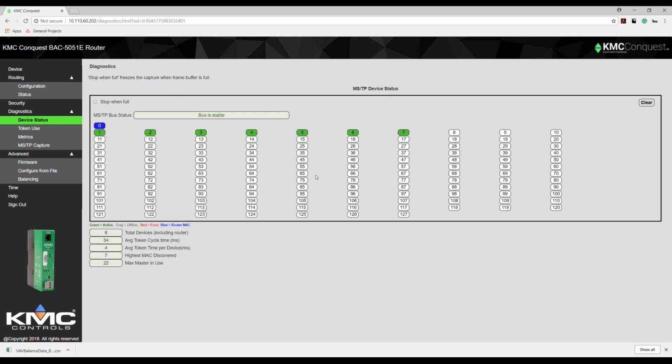So we're eating up more time on your network. We're passing that token a lot more slowly than we otherwise should, and things just don't happen as fast. Generally, you can still have reliable communication, but if we're making off-panel requests, and especially when a front end is online looking for data to put on a graphic, you're going to see some slower response on your graphic.